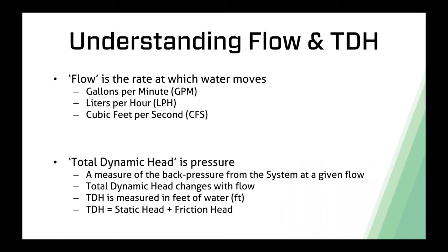Total dynamic head is a kind of a long and complicated term for pressure. Pretty simple concept, actually. The total dynamic head is a measure of the back pressure that the system applies to the pump. So when a pump kicks on, it tries to push water into a piping network. And the piping network responds by pushing back on the pump. And so the pressure with which that system pushes back is called total dynamic head.